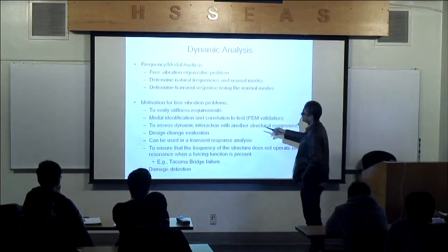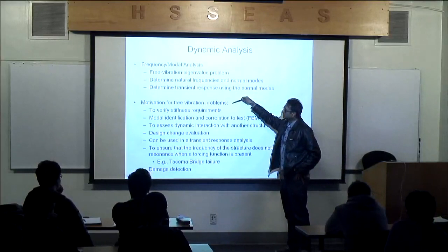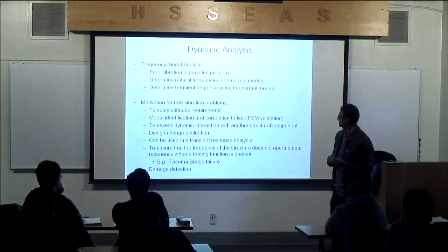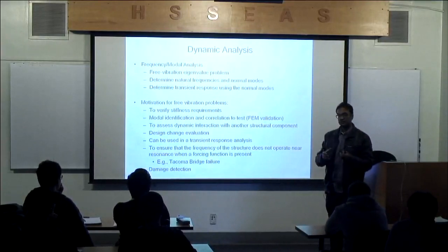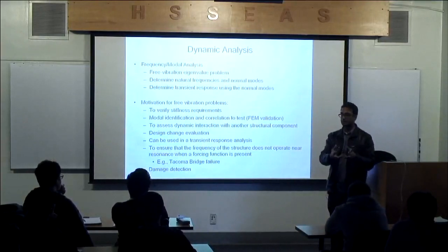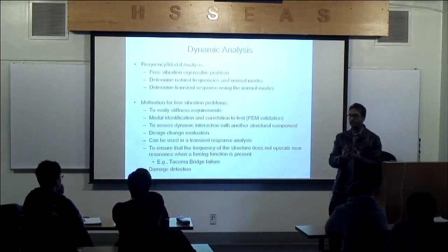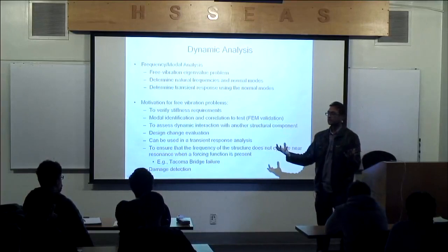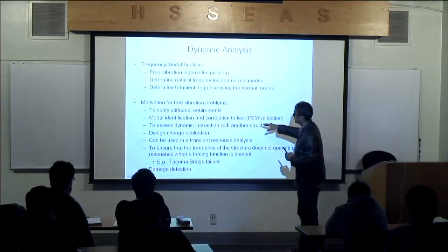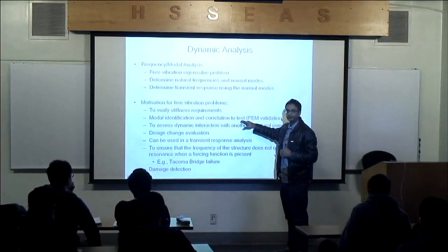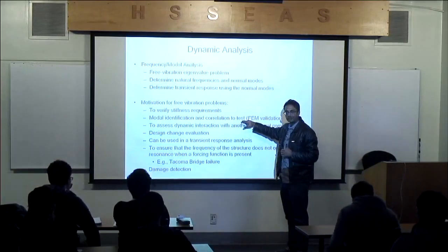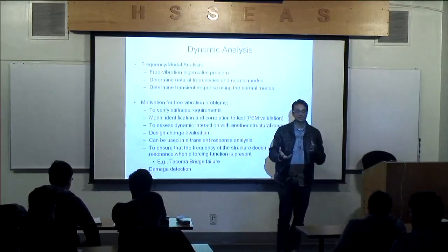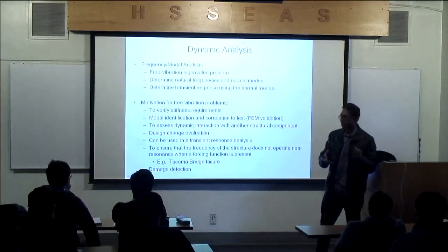So what is the motivation of analyzing free vibration problems? You can verify stiffness requirements. That's one possibility. You can take your model that has dynamic characteristics, and we'll talk about that, and compare it to reality. Does my model compare well to reality? We can determine the dynamic characteristics of the actual structure by measuring the modes and the frequencies and comparing that to your finite element model to see if they make sense, one against the other.